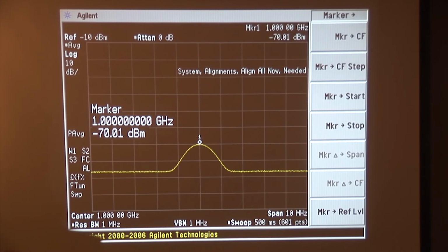And we know that any time the signal level is more than about 10 dB above the background level, we don't really have to do the anti-log corrections on the measured power. We can take it as is. So we have improved the signal to noise ratio here by about the difference between 16 versus 3, so about a 13 dB improvement in signal to noise ratio.